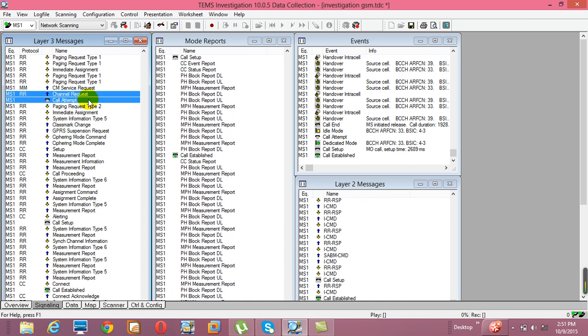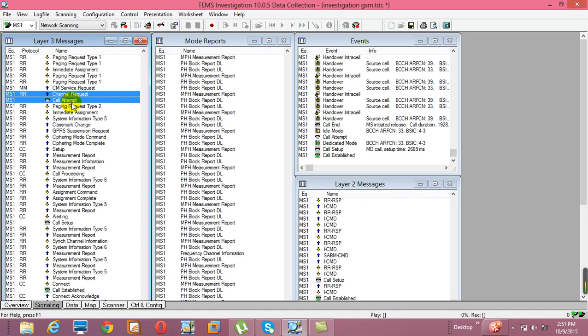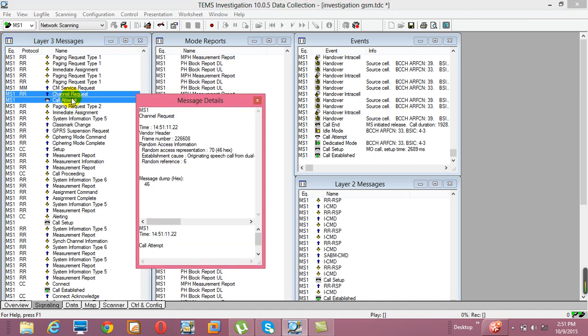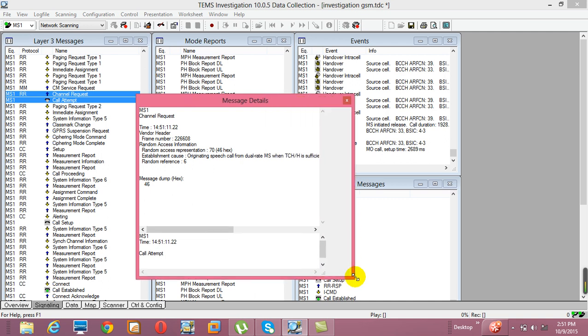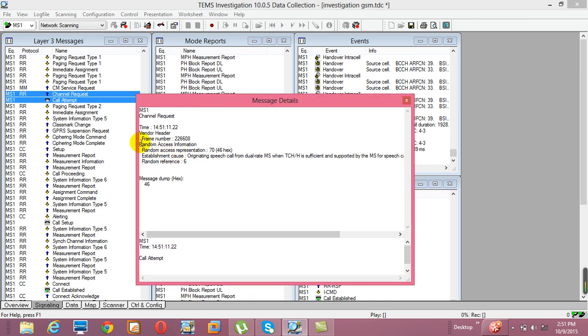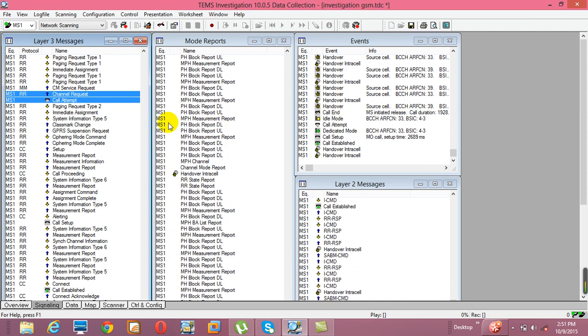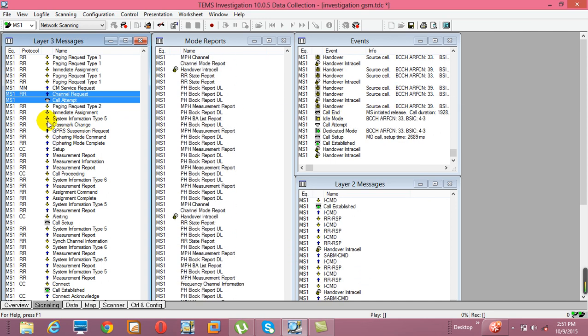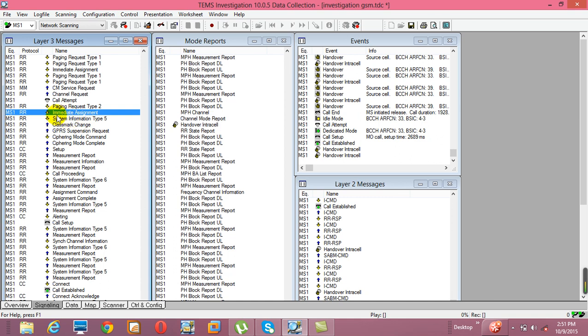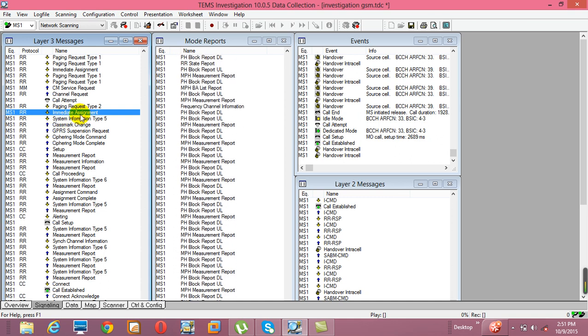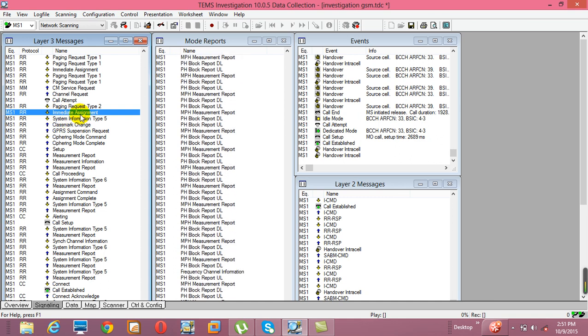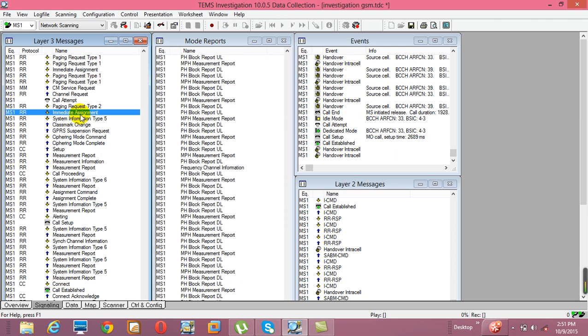Now once I made a call, the request is going on a RACH. So let me click and see. See, when I dial a number and push the call button, the request has gone on the random access channel. The request has gone to the network on the RACH, and the RACH should get answered by the AGCH. Immediate assignment with the AGCH channel. You can see the immediate assignment, and it allocates the channel type to the mobile station, which is the SDCCH channel, standalone dedicated control channel.